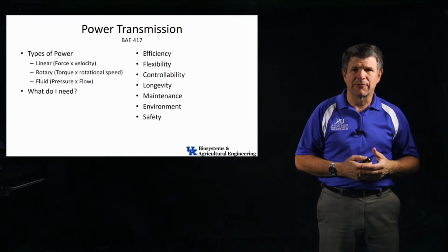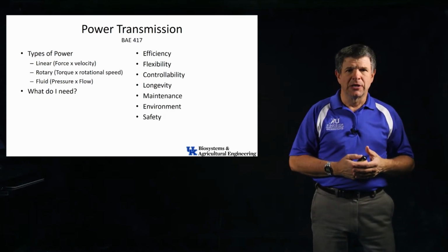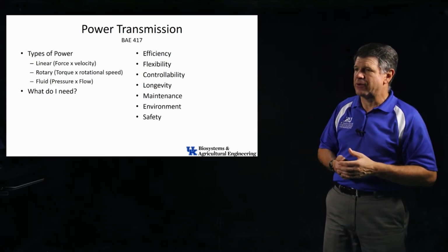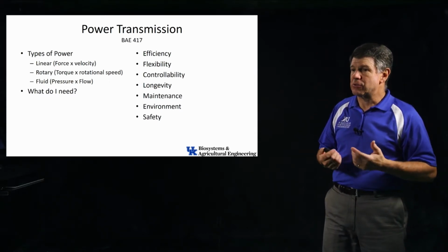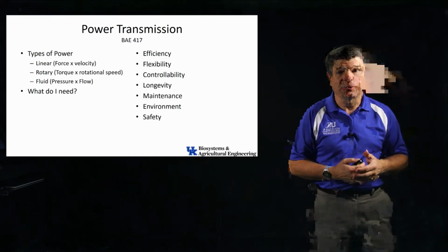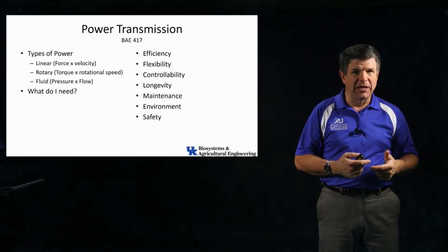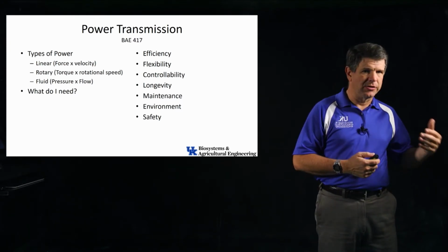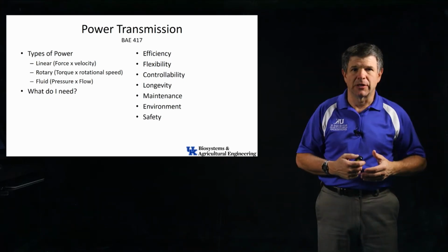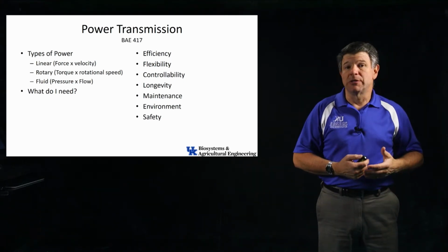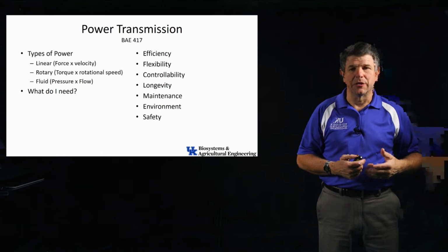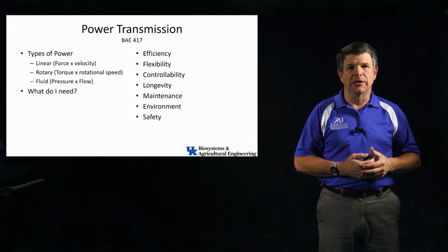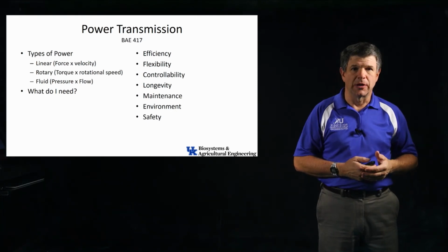As we look at these different power transfer methods, keep all of these things in mind and be thinking about what's the right thing to choose, because a lot of times I can do it a lot of different ways. I could use different types of mechanisms to transfer the power: V-belts versus chains versus hydraulics, a fluid power. Which one is going to be cost effective? There are a lot of things that go into that decision in terms of what I choose for a certain application.